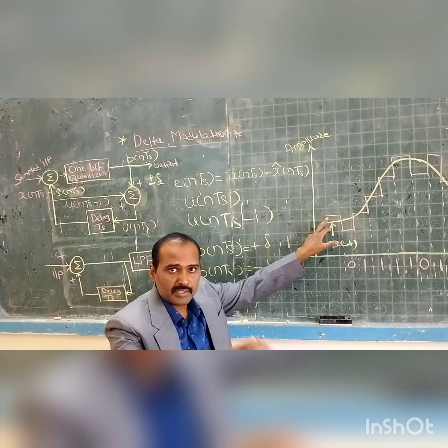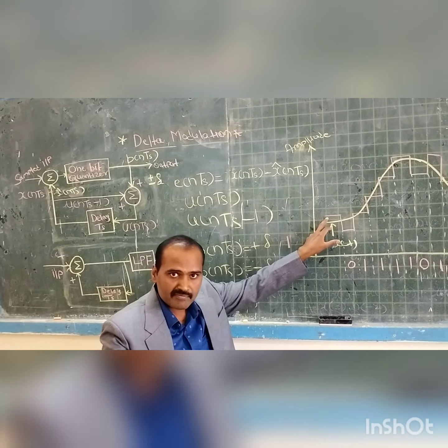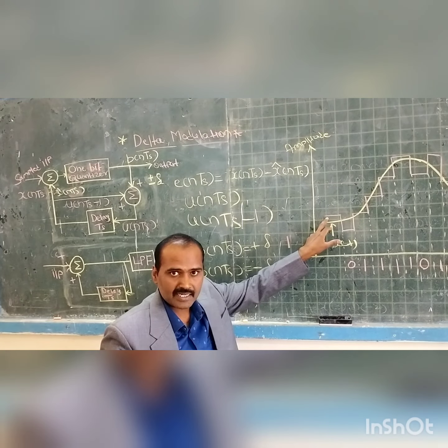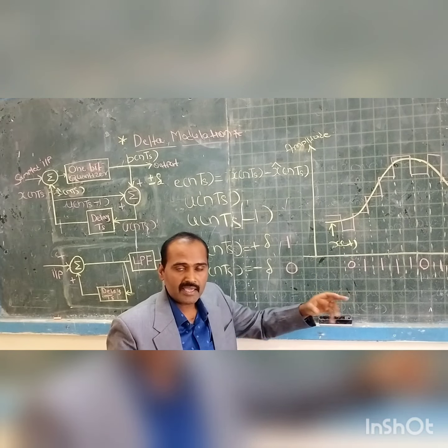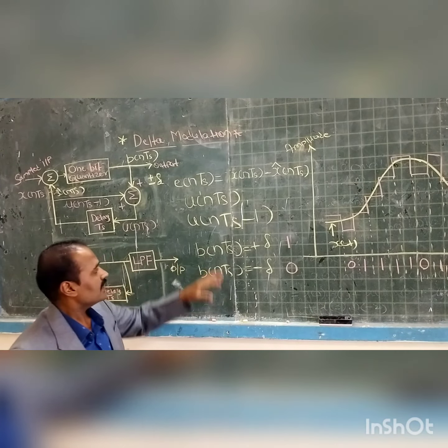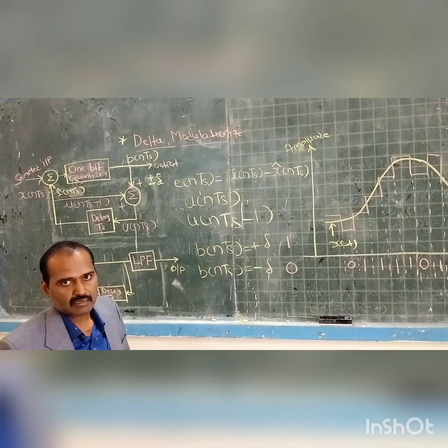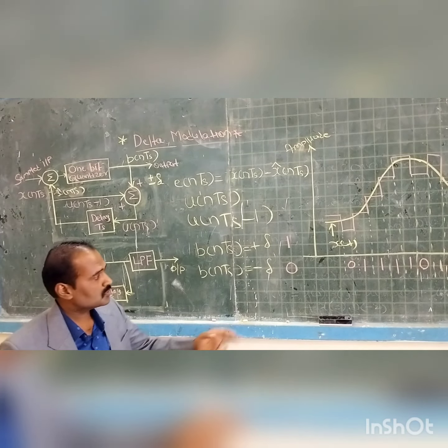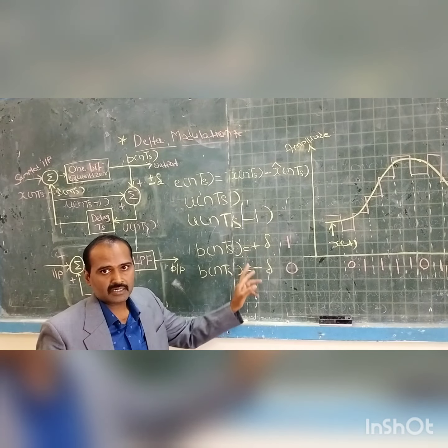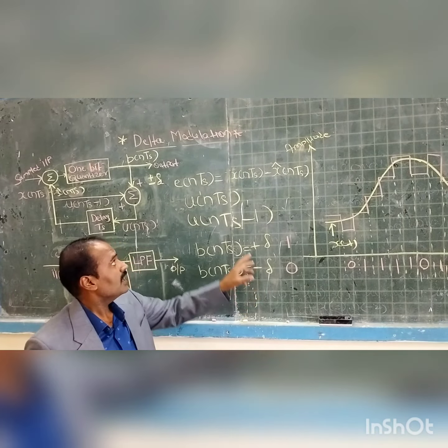During each signaling interval, it checks whether the difference is positive. If so, the step size is incremented by plus delta. If the difference is negative, the step size is decremented by minus delta. In this way it works as a one bit quantizer, producing either plus delta or minus delta. It depends upon the amplitude of this difference signal.